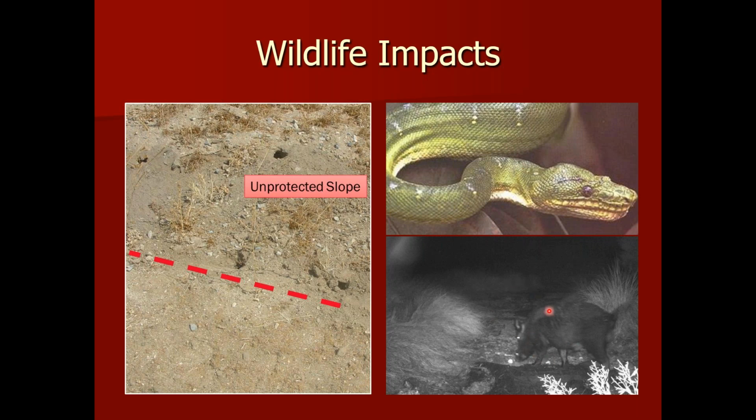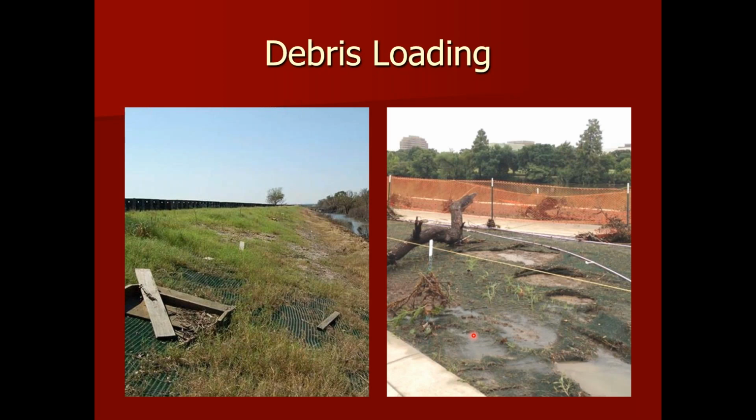And good old hogs, feral hogs. This study was done down in Louisiana, I'm sorry, to investigate the strength of materials, buried garbage literally underneath the mats, and videoed then over the course of several weeks what would be destroyed and what wouldn't, and we were able to correlate the effort that the hogs would take to dig something up back to the performance properties, index properties of the TRM itself. Debris loading is very important.